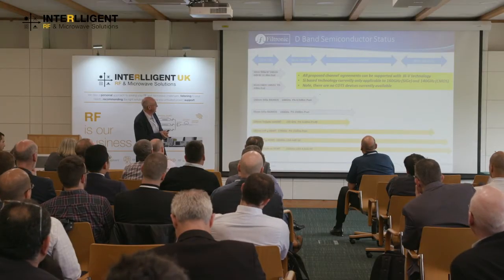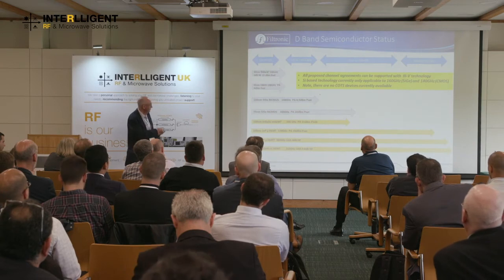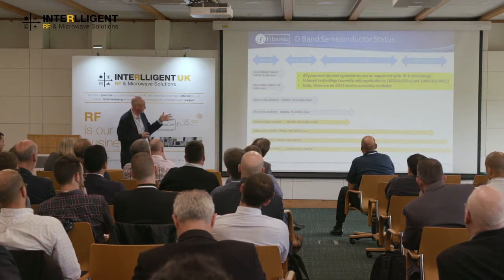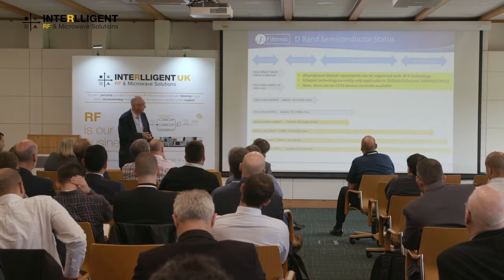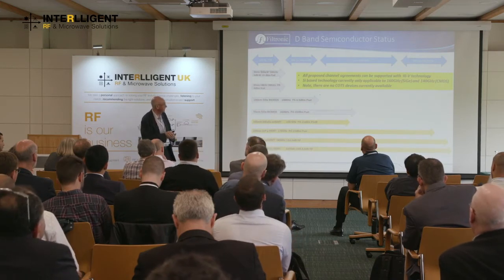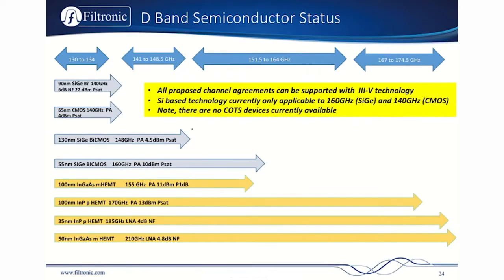That's really the situation for D-band. Again, we're talking about III-V semiconductors. And the technology is already there with indium phosphide, albeit at a very early stage, not commercially available, but the technology is there to go up to 175 gigs. Silicon's getting there, can probably go to about 160 gigs using the best BiCMOS processes.